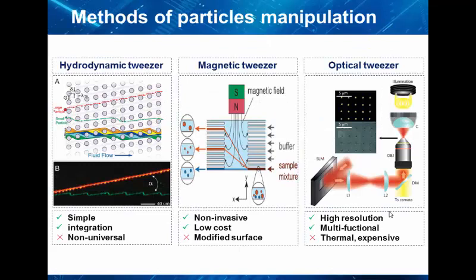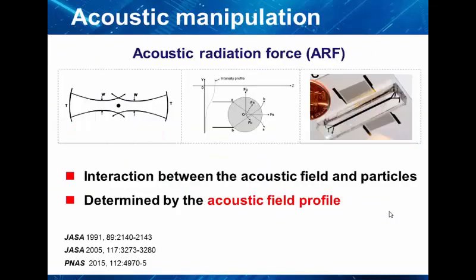Compared to the micropipette and microtweezers, due to the non-contact property, methods of particle manipulation based on external physical fields are dominant. Among these methods, hydrodynamic tweezers are simple and integrable, but non-universal. And magnetic tweezers are non-invasive and low cost, but they need to modify the surface of the particle. Optical tweezers have a high resolution and are multifunctional, but they are also thermal and expensive.